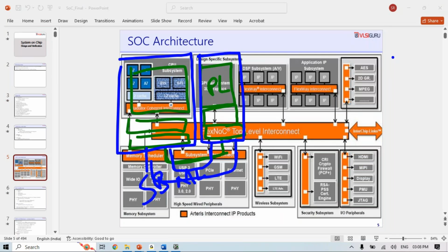Till this point, have you understood what it is doing? What the die to die adapter layer does is, once you start the system, some kind of negotiation happens between the die to die adapter layers on both sides, where they try to understand their capabilities. Each advertises which protocols it supports, and they agree upon a specific protocol. For example, in this case, they agree upon raw format.